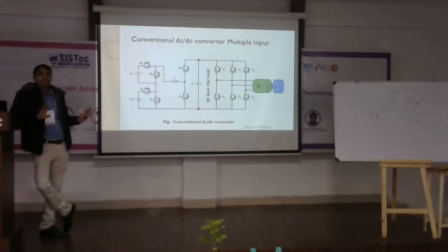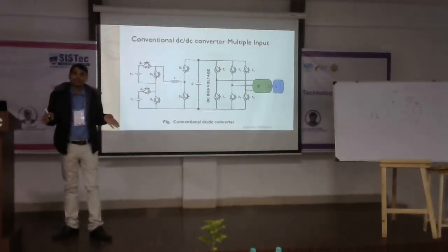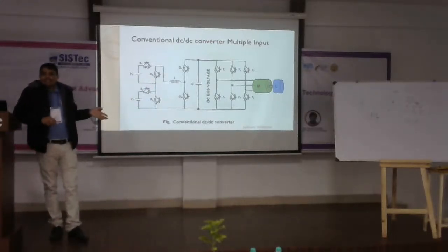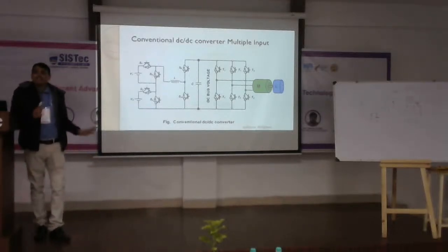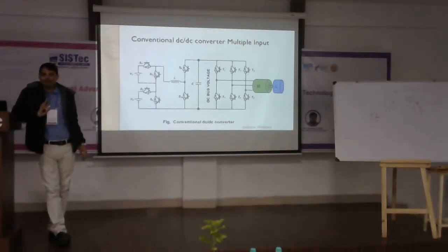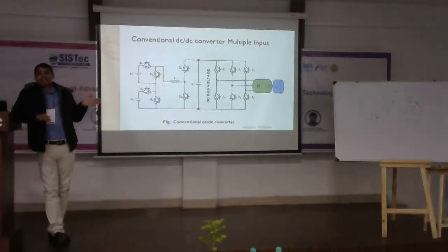Right, that is what we are doing. If you have used a fast charger for charging an electric vehicle, what did you do? You had a battery, right, and AC was your source. In the grid there is generally AC supply, here in India there is no DC grid, the AC grid is there. From AC you made DC by using the converter and fed it to the battery, isn't it? So when you connect this type of converter, and if you are feeding to the grid, again the bidirectional converter will work, DC to AC, and from AC it goes into the grid. So this bidirectional power conversion, what we are considering, converter is there, and the converter is a major source of harmonics.